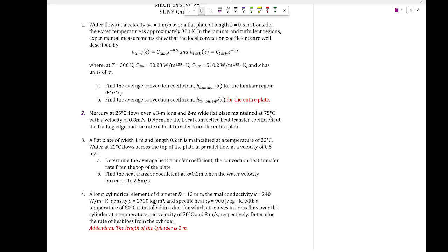Now here's another thing: the values of this H. You remember the sense and nonsense values, right? If you're seeing values of H that are way too high, you know it's a nonsense value. If it's like 0.00 something, it's a nonsense value. Usually, that is the convection value for natural convection, and if you find a nonsense value, most likely you are making some error in the calculations here, okay, with the units or something.